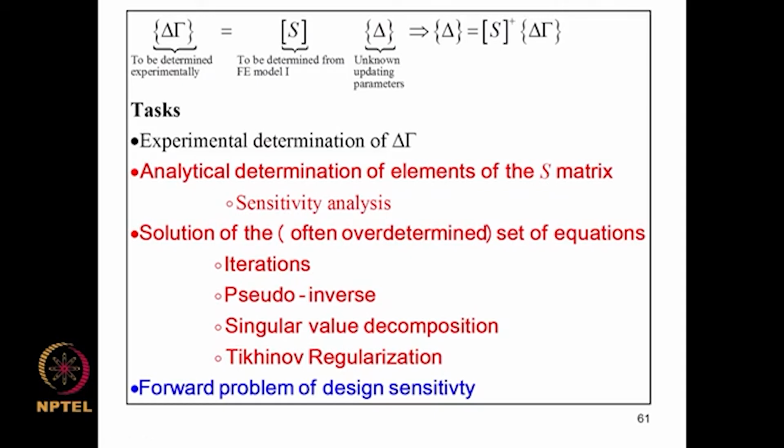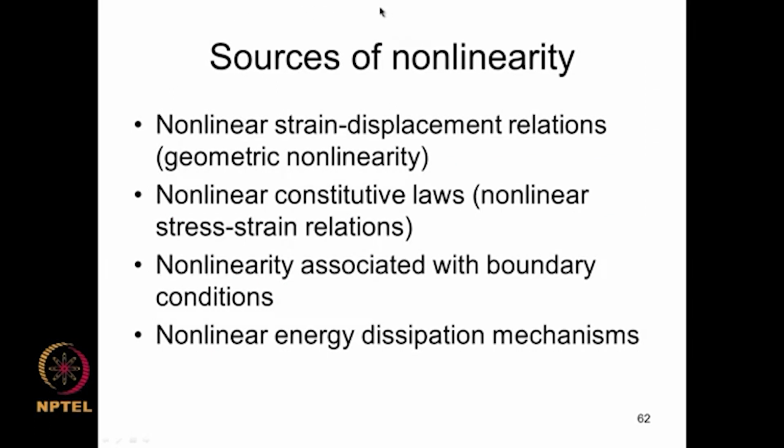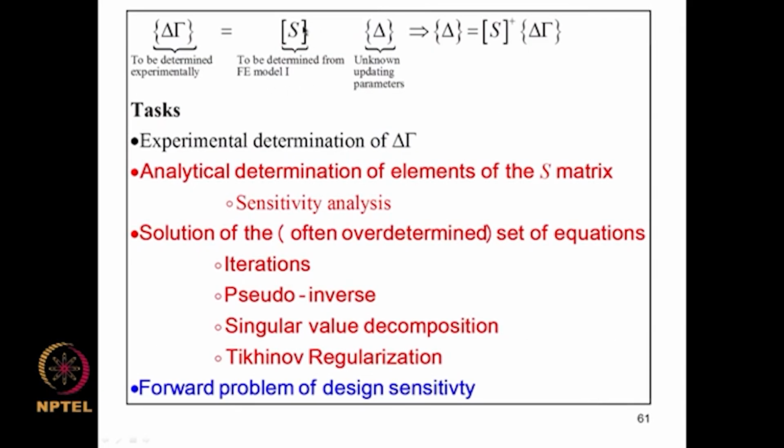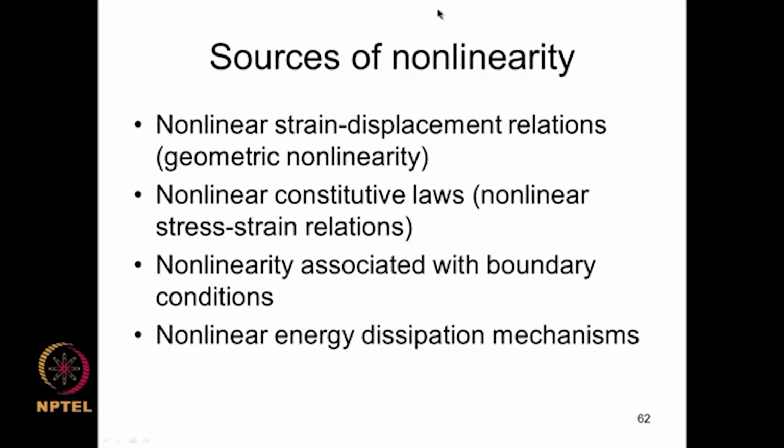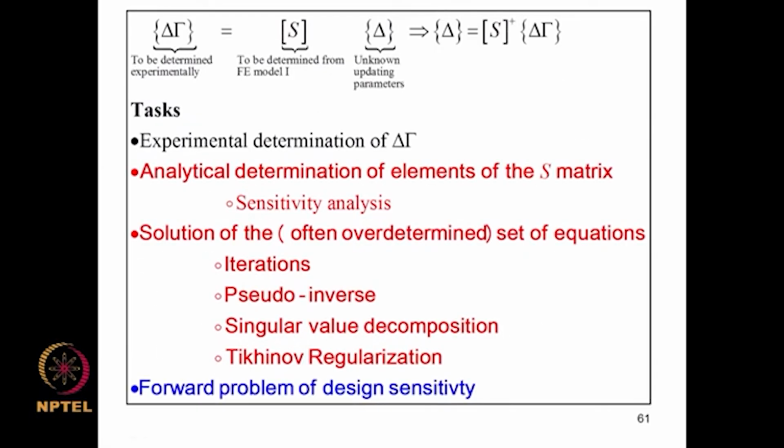So, we derived the updating equations in terms of changes to be made to system parameters based on observed changes in certain system responses, and these we showed are connected through a matrix known as the sensitivity matrix. So, we considered several issues here: how to formulate this S matrix, and how the resulting equations will often be a set of overdetermined equations that require special techniques to solve them. We discussed pseudo inverse method, singular value decomposition and Tikhonov regularization approaches for dealing with this class of